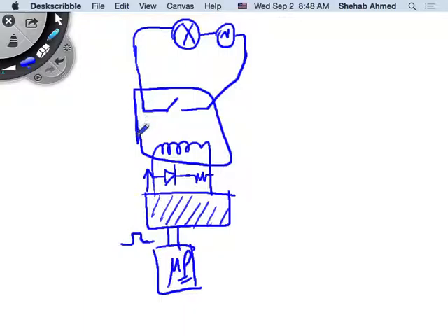Again, this relay has continuous current, right? If your amplifier circuit disconnects the current going to the relay without having another alternative path for the current to flow, then you will burn your amplifier circuits, for example, right?